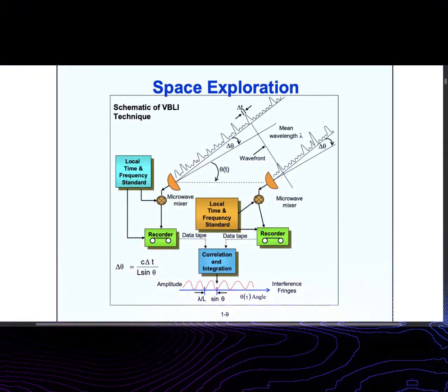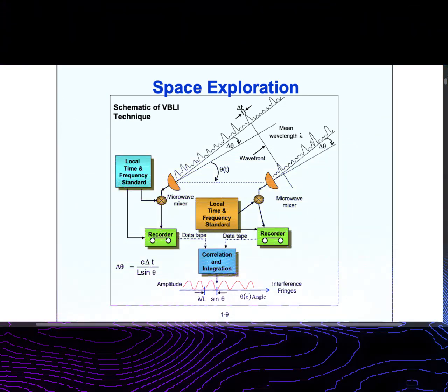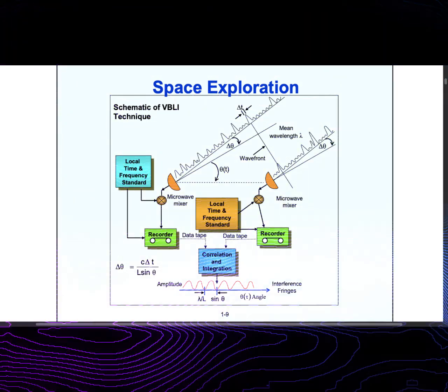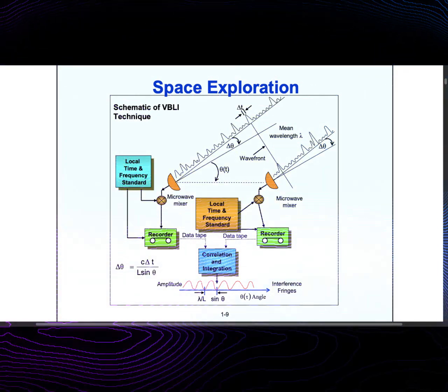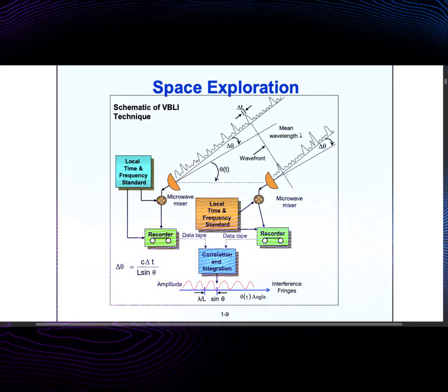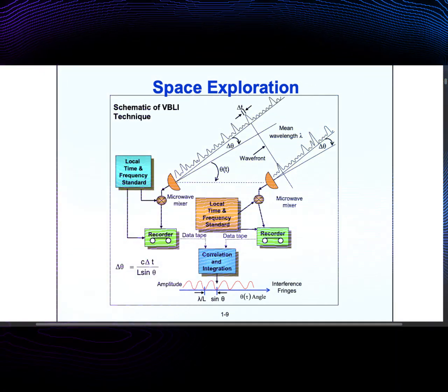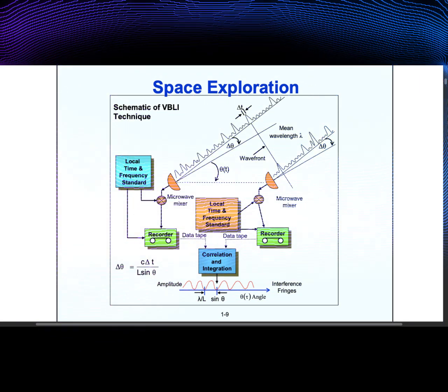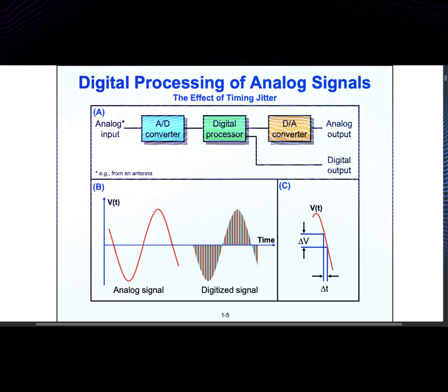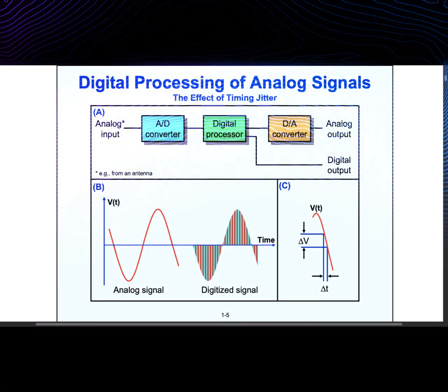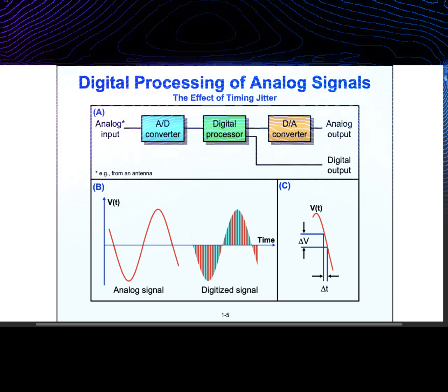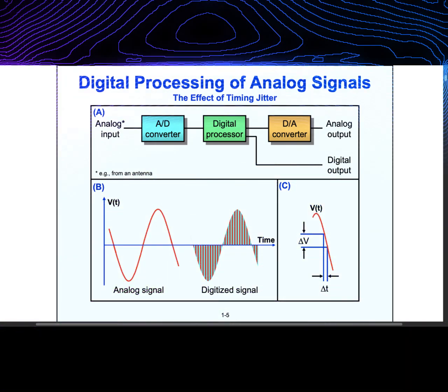What makes quartz crystals so important? Key features: the Q factor and stability. The resonant loss of quartz is extremely low, resulting in an extremely high Q factor. The intrinsic Q of quartz is 10^7 at 1 MHz. Mounted crystal resonators typically have a Q factor ranging from tens of thousands to several hundred thousand, orders of magnitude better than the best LC circuit.